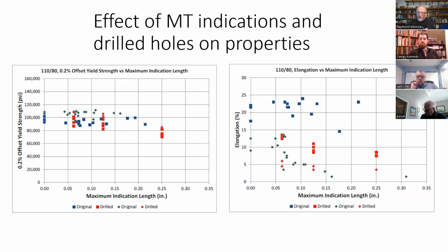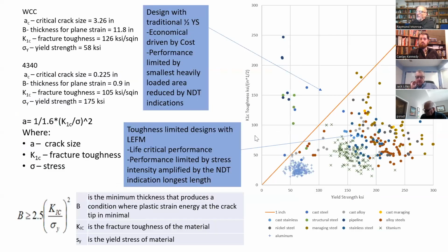And this is the fundamental reason. We talked last time about the fact that the test bar really was supposed to be a test of how good the steel was, not how good the bar was. And so if you had a bar, even today in ASTM, and you can see a flaw in the fracture surface, to qualify the heat, you can throw that bar away and test another bar, because you're not interested in, can I make a good test bar? You're really interested in whether or not the steel meets the properties you would expect. So this, I think, is really a critical set of concepts for people.